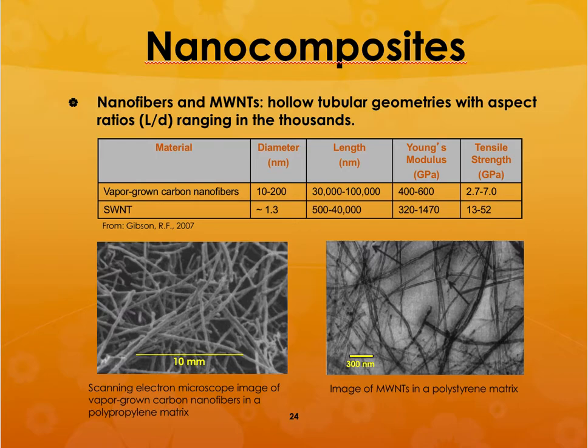a gram. So if you want to add, say, more than 1% or 2% of that in a composite costing about, say, 300 or 400 or maximum $500, you are doubling the cost of that component with just the addition of 1% carbon nanotubes. And does it really result in that much improvement in these properties? Difficult to say. So it was a very big challenge.